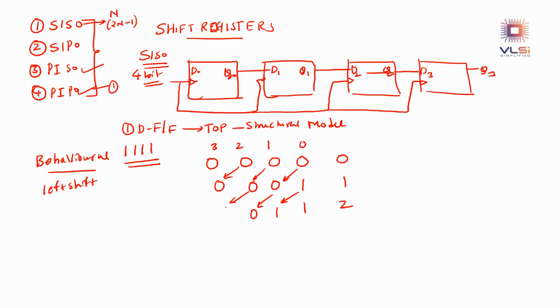At the third clock cycle, one bit will be inserted and this will be shifted, so you will get 1 here, 1 here, and 0 here. At the fourth clock pulse, all the serial data will be loaded. From the fifth clock pulse onwards, you can take the bits out serially, until the seventh clock pulse.